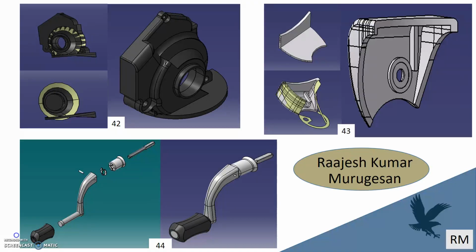Also it's going to sit over a groove in the rotor, so I designed this part in the assembly workbench by taking the outer curves of the groove for the external sketches to get the desired shape. Here I just used two different workbenches: the part design workbench and the surface and shape design workbench. In this I used one tab with part design and one tab with surface design to check how exactly those two differ. And up next at the bottom is the handle assembly.